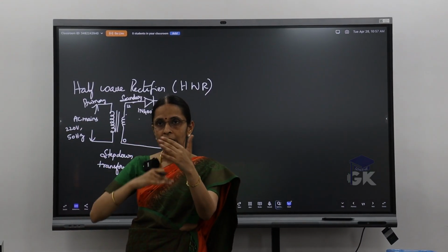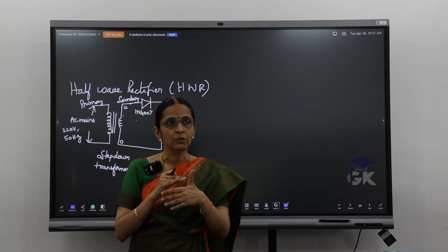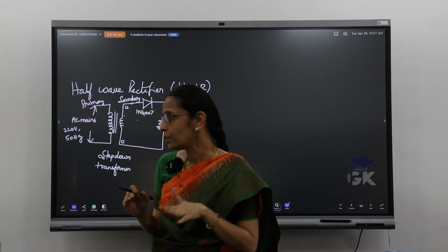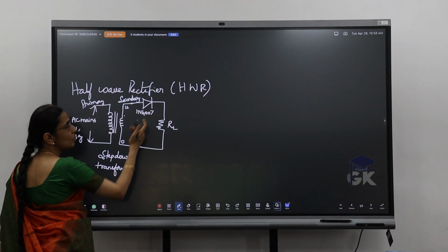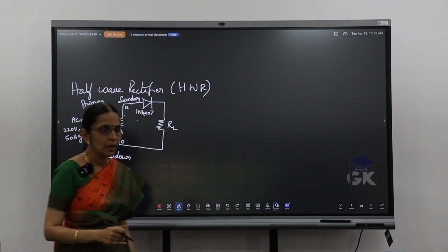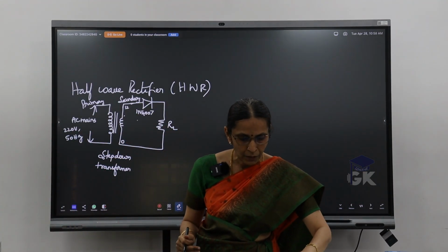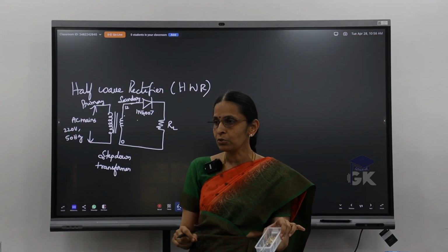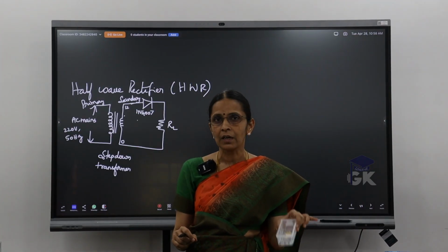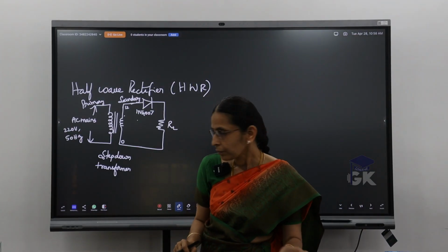We are not using both halves, just 12 and 0. So this is the transformer, followed by your diode, the diode with the plastic package, that is my 1N4007, your rectification diode.